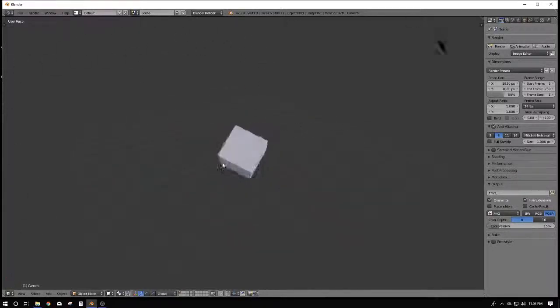so this is to orbit and rotate around an object. But say you wanted to just move side to side. What you can do is hold Shift and click down on the middle mouse button, and that will allow you to pan left and right, up and down. It's really helpful for when you're trying to just get across a larger surface or trying to get the right view that you want, and you don't want to be orbiting around. And it allows you to move that focus of the orbit as well.